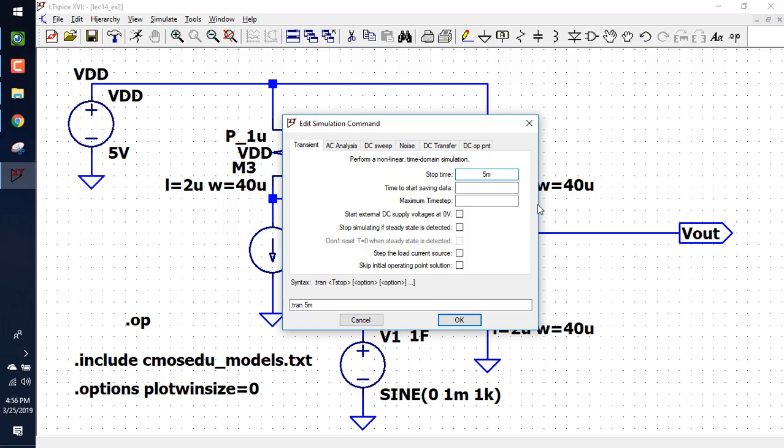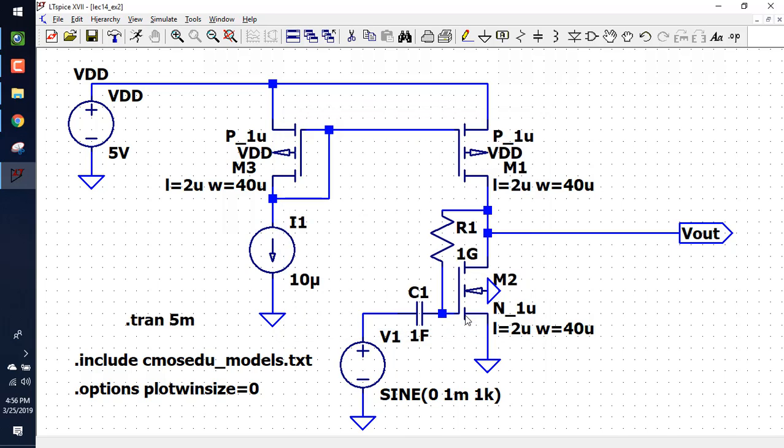Now I'm concerned about a lot of things. I have a mistake here we'll talk about in a moment. But I'm concerned that this voltage won't be steady state. So if you look at it, you see what the voltage is when I did the dot OP? You see it was 876.14 millivolts down in the lower left corner. That's the DC point I want my transient to start at.